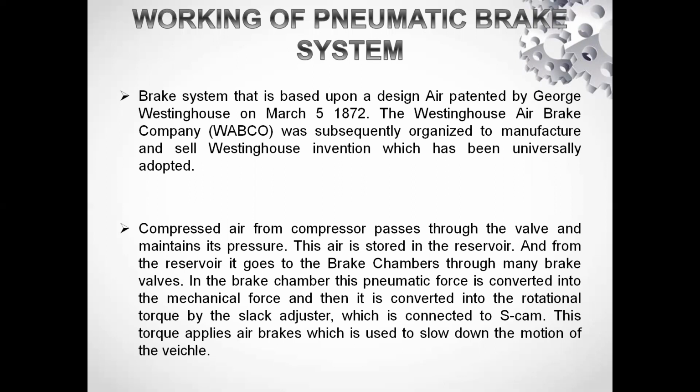You can see the working. Compressed air from the compressor passes through the valve and maintains its pressure. This air is stored in the reservoir, and from the reservoir it goes to the brake chambers through many brake valves. In the brake chamber, this pneumatic force is converted into mechanical force, and then it is converted into the rotational torque of the slack adjuster, which is connected to the S-cam.